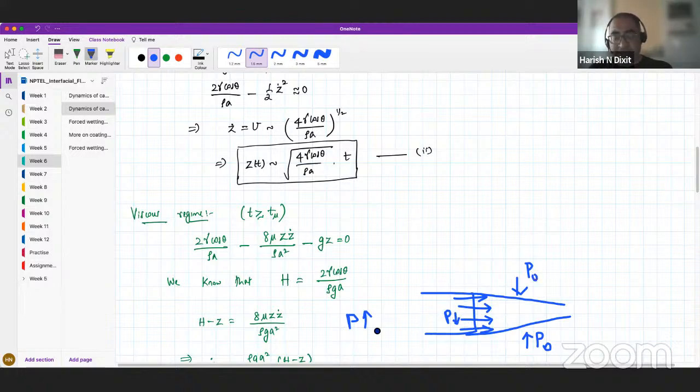So what you're actually doing is two things here. The pressure in the combustion chamber is very large, and as it exits the nozzle, its pressure is continuously decreasing. Rocket engineers basically achieve this by expanding the gas to lower the pressure. The idea is that you want to lower the pressure and bring it as close to the atmospheric pressure as possible.